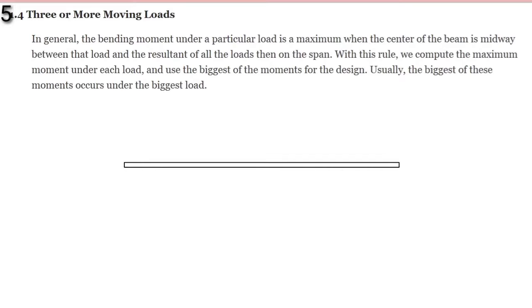So, how do we lay this out on the beam? Let's simplify first, so let's start with 2 loads, since it is the same idea as the 2 moving loads and what is said here. So, if this is the PB and this is the PS, this is our scenario from the last topic on 2 moving loads. And this is the fixed distance.